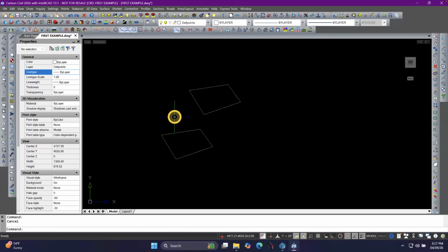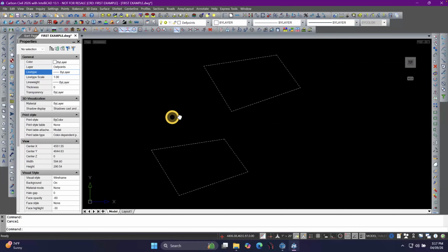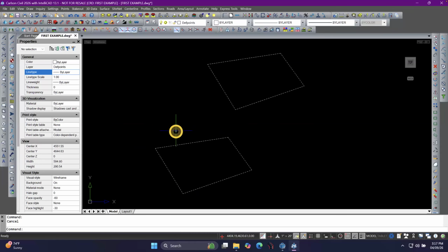All right, so again, we're going to be very polyline driven, 3Ds and 2Ds. And the 3Ds are going to be what we're going to use to draw break lines and edges of parking lot, setting up things that have elevation on the ground. And then when we put those together and model them into a surface, you're going to see that turn into what that surface would be.